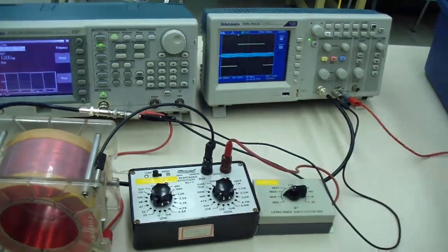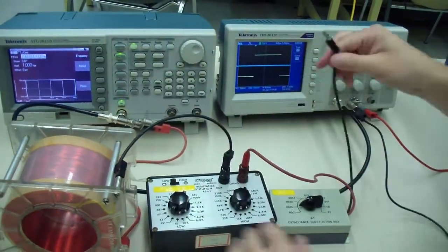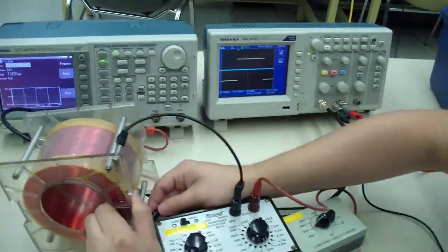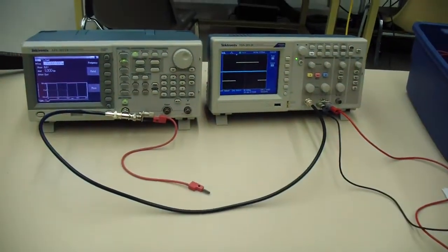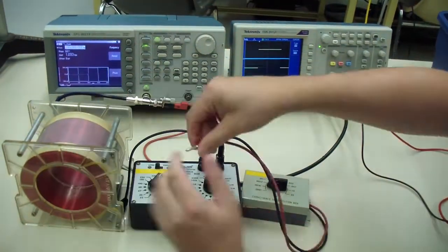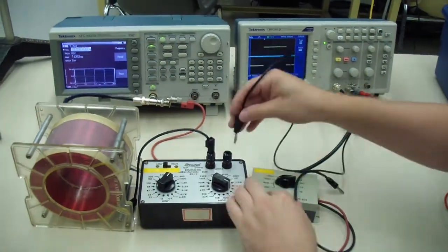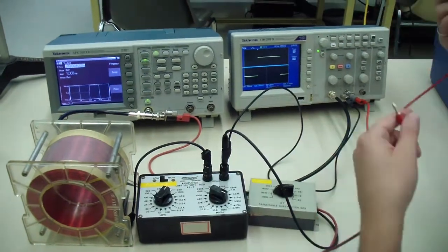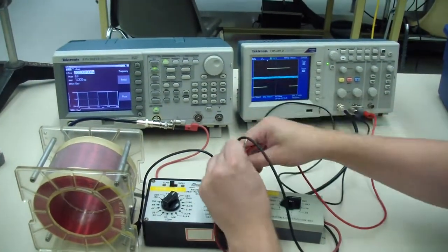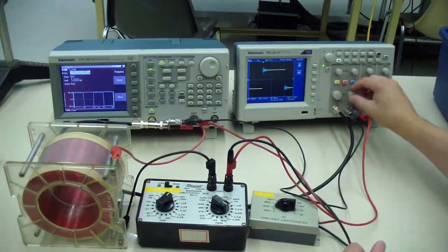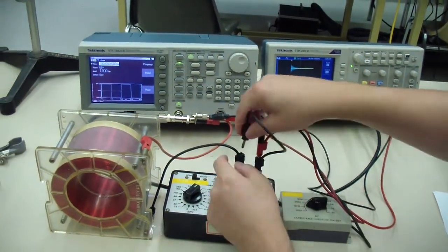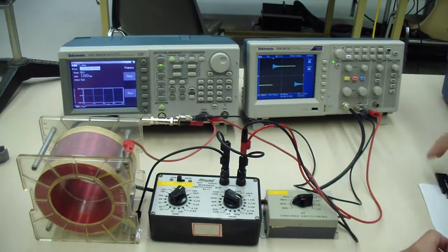Remove the oscilloscope from the capacitor and the function generator from the circuit. Make sure to reattach the inductor, resistor, and capacitor in series for future use. Replace the entire circuit with the second RLC circuit. Add the oscilloscope across the capacitor and break the circuit to add the function generator. Short circuit the resistance box and measure the natural frequency of the circuit as before.